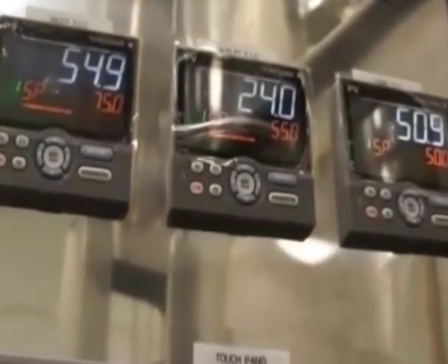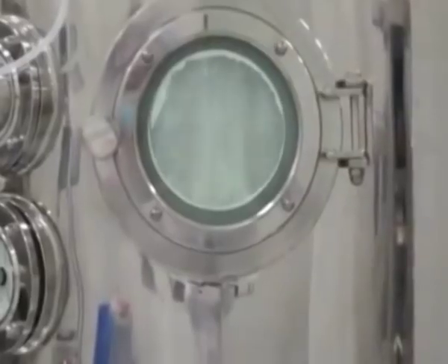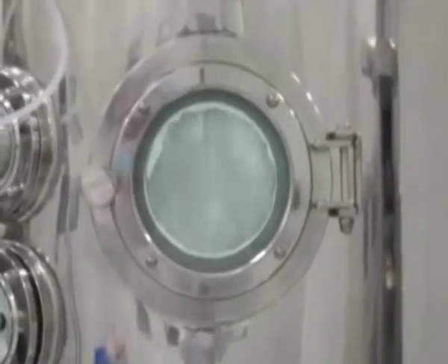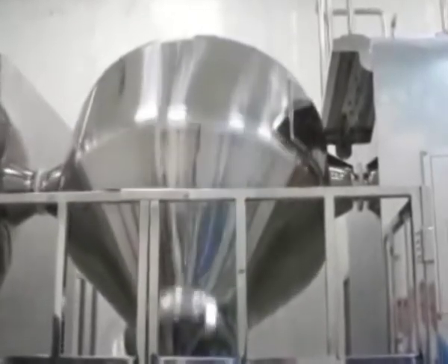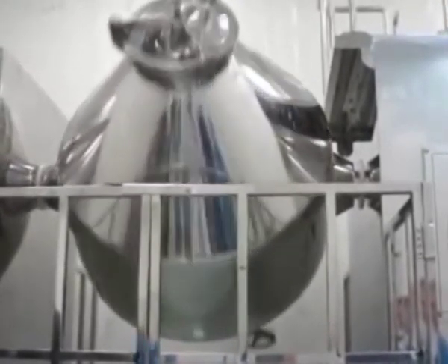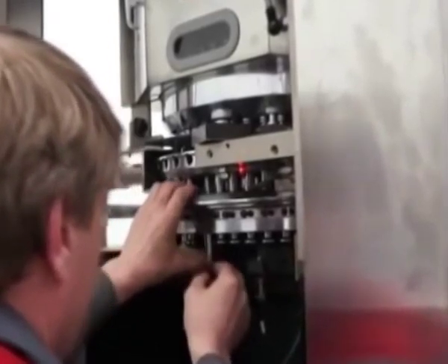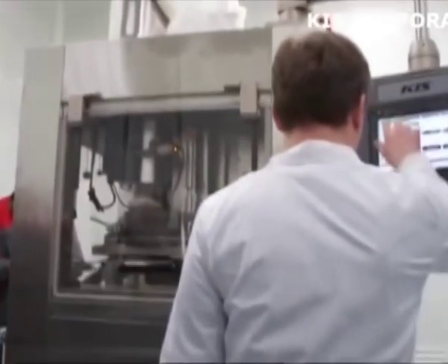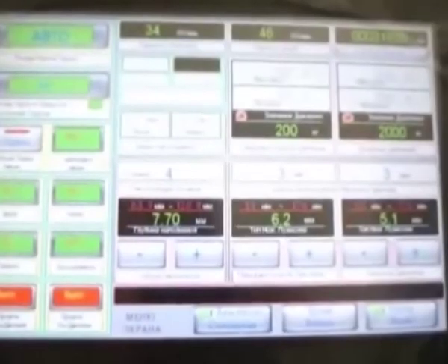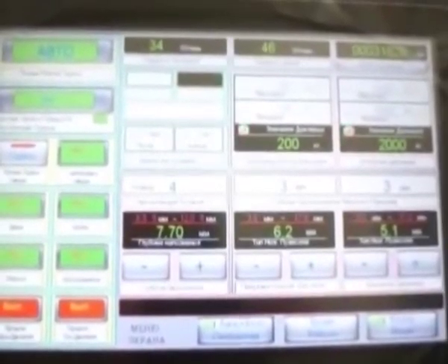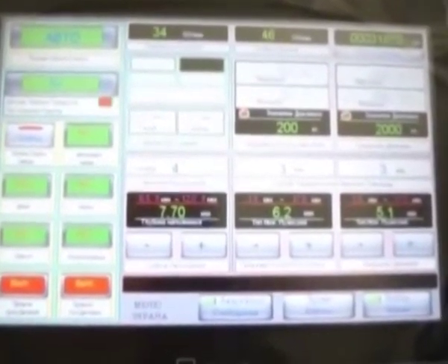The coating section shall be made dust free with a suitable exhaust system to remove excessive powder and fumes resulting from the solvent evaporation. It shall be air conditioned and dehumidified whenever considered necessary. A minimum additional area of 30 square meter for the coating section for basic installation and 10 square meter for ancillary area is recommended.